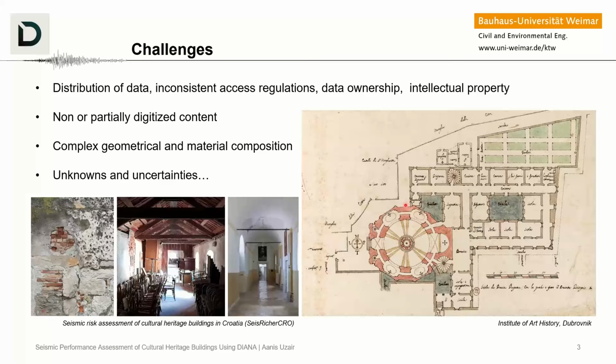One particular aspect that cannot be excluded is how the connections are formed between wall to wall, between wall to floor, and between different structural components within the walls. But this is extremely difficult to model because these connections are largely unknown, and assuming a property for the interface rather leads to uncertainties than making the analysis any better. So we have to be very careful when modeling connecting parts with each other in the software.